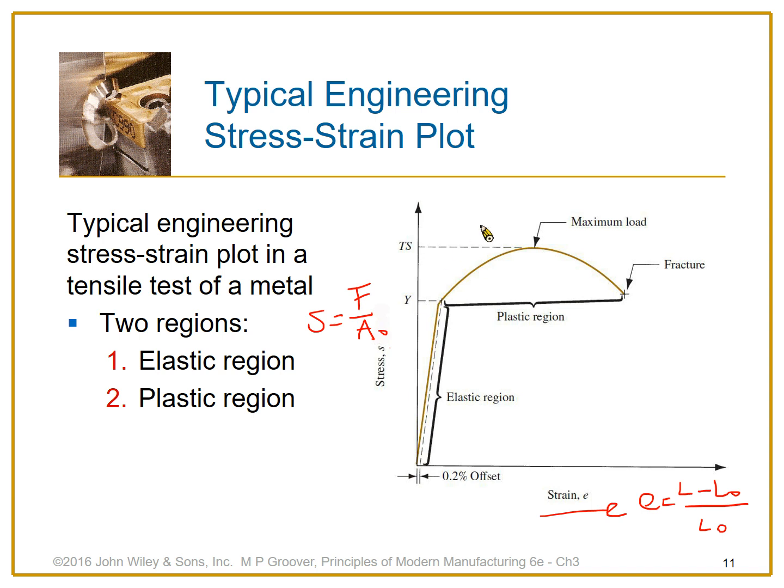That's one particular material, and as you apply more force, the strain also changes. In the very beginning, you apply force and it changes, but it changes very constantly. This particular area we call the elastic region. That means if you apply the force, you change the size, but when you release the force, the size goes back to the original size. That's why we call it elastic. Once again, you apply the force, you change the size, but you release, it comes back. Until a certain point called the yield stress. After this point, it does not come back once you release.